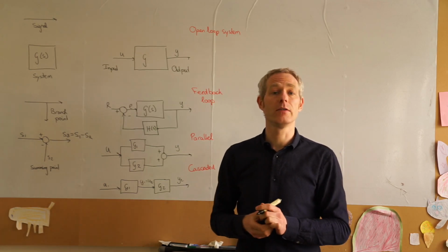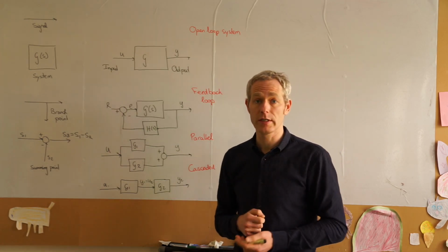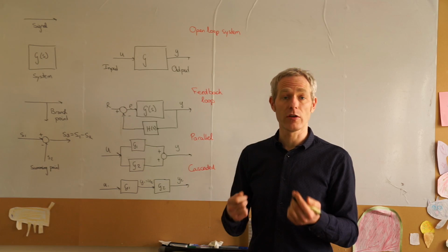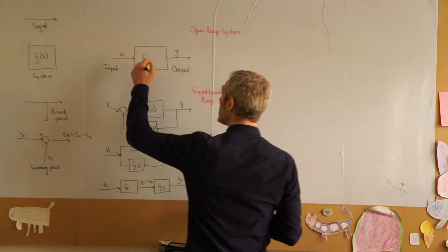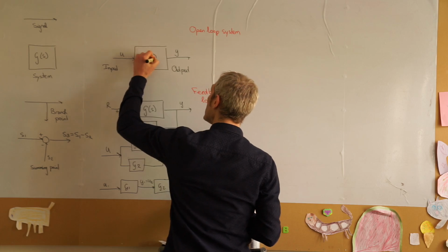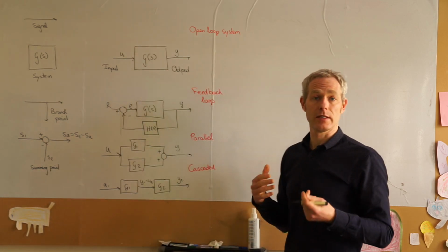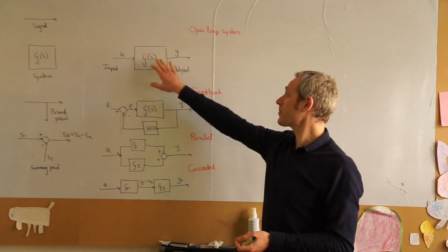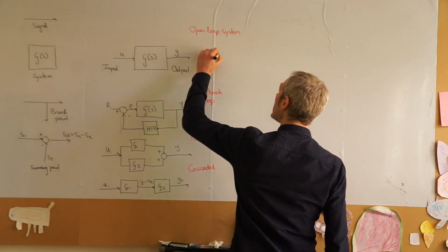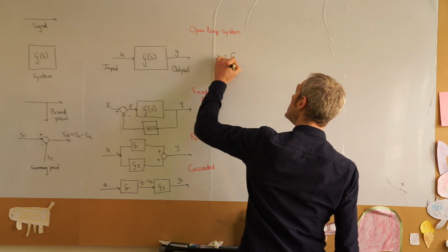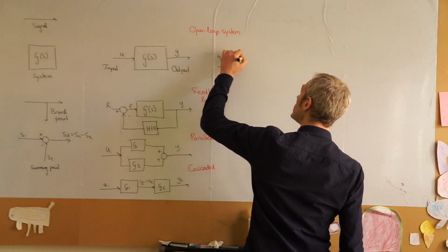In fact, what you need to do is use the convolution integral, which is a lot harder than what we can achieve if we use the Laplace or the S domain, where we write everything in terms of S, our complex variable, and then we can simply write that the output is G times the input U.